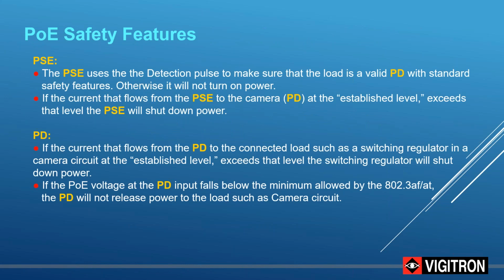Talk about the safety features, which we've touched on before. So once again, if a complete circuit is not achieved, if the PD does not send out the signals, if the PSE does not recognize the PD, in order to maintain safety, in order not to incur a short, the product shuts down and it drops off the power.